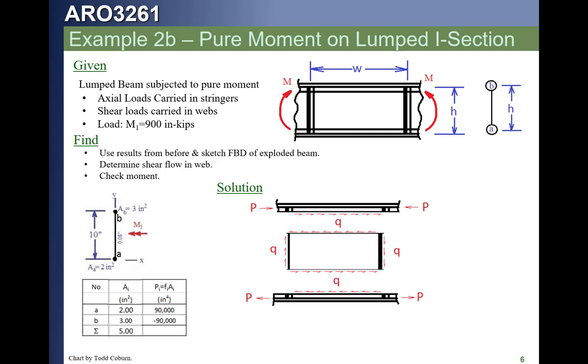Now we're ready to draw our vertical stiffeners. We've got one over there and one over there. And we can see that the shear flow along there is 0, and that would correspond with any shear. Now in this particular case, we found our shear flow is 0, therefore our force will be 0.